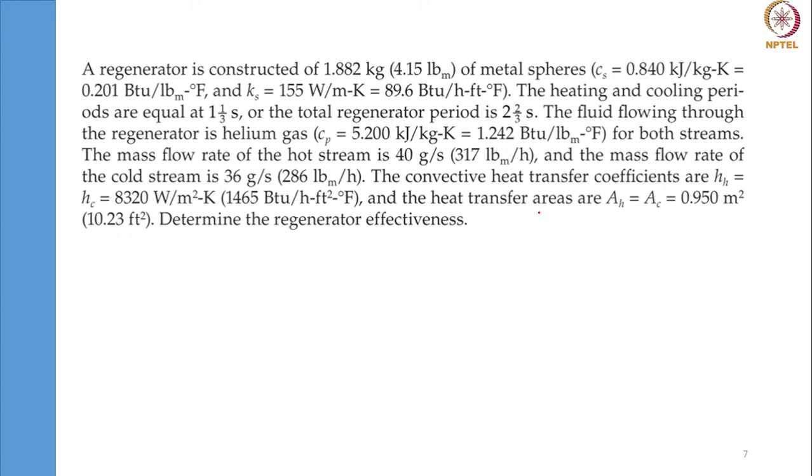On both hot and cold sides it is helium gas, with a mass flow rate of 40 grams per second on the hot side, and 36 grams per second on the cold side. The heat transfer coefficients on hot and cold sides are also given, and the heat transfer surface areas are also given. We want to determine the regenerator effectiveness. I'll give you a few minutes of time. You can work it out and I'll show you the solution.